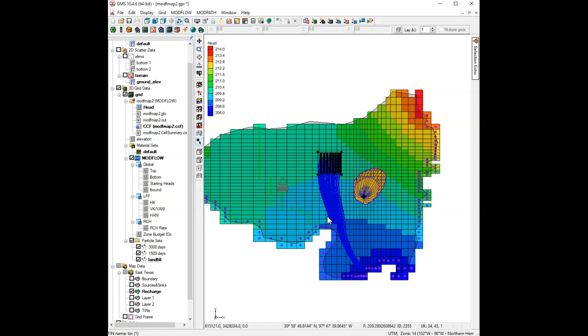So now you'll see that these path lines are going forward in time, and that creates a pretty dense set of path lines. And if I decide, maybe that's a little too dense, you can always go back and hit the delete key and delete those, and then we can do that again. And in this case, we generate particles at selected cells. I'm just going to go with 1 particle per cell in this case, and that should give us plenty. Okay. All right, now you'll notice that all of those path lines go down to the river at the bottom.